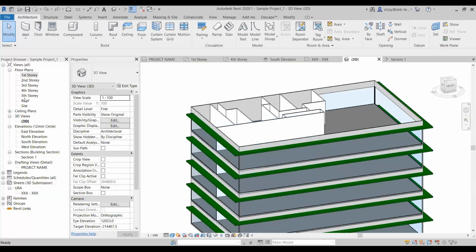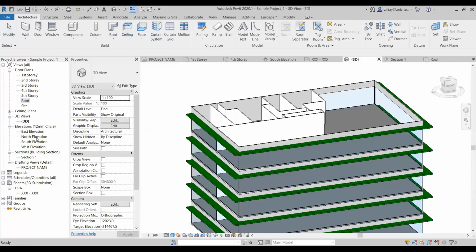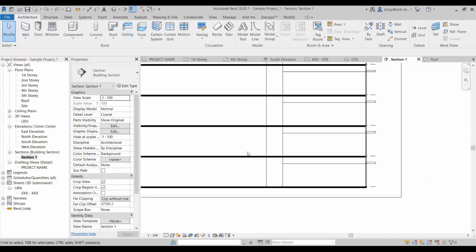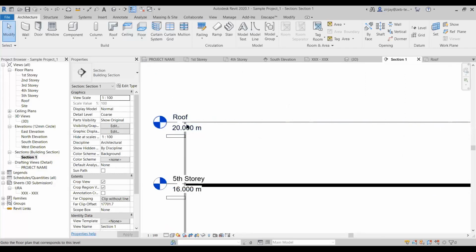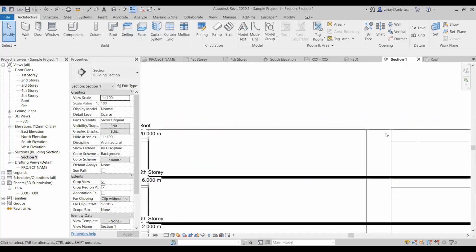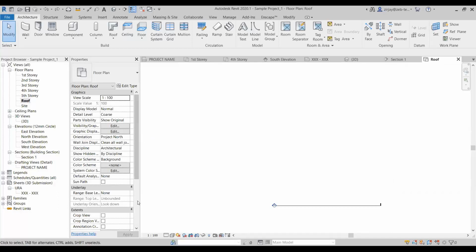So we're just gonna go ahead and do that. We're gonna right click on the roof level. Oh, as you can see, it's not visible. That's because everything is only up to the, it's best shown on section. So right now, we cannot see anything on the roof level because we're only seeing up to this point. So by right, it doesn't show those elements under this particular line, but there's ways to adjust that.